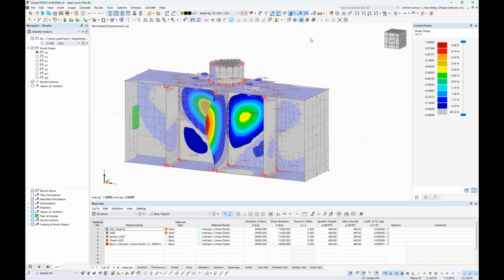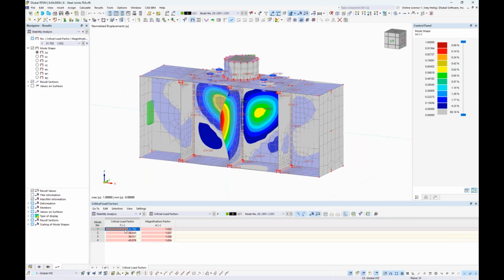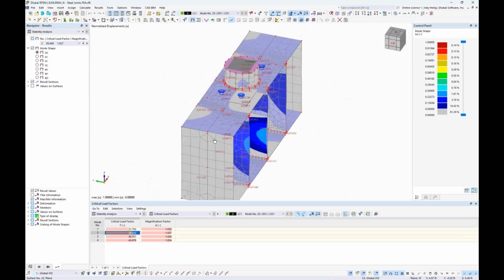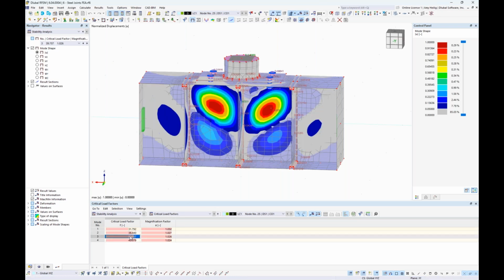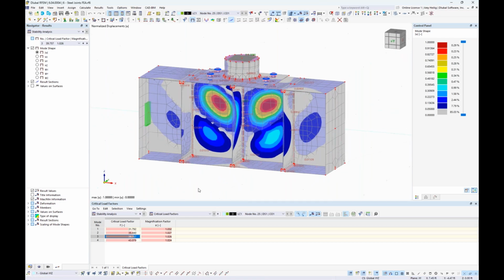So every example that we've seen up until now is the same workflow that's going on underneath the hood. Under the stability analysis results, we can view 4 different eigenmodes, the critical load factor of 31.729 before we see the buckling of that stiffener plate, and then also the relevant mode shapes here with slightly higher critical load factors. So again, we start to see concern for the buckling of these web elements. Pretty unique and powerful, what's going on underneath the hood for any connection type, because of the ability to generate this FEA.